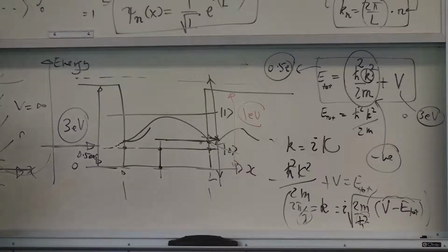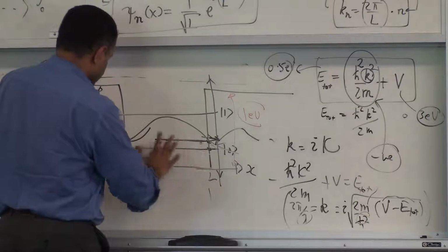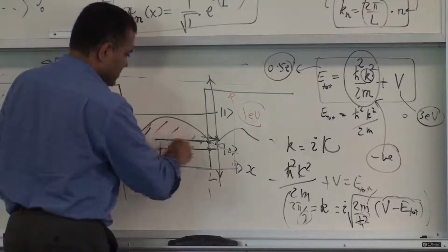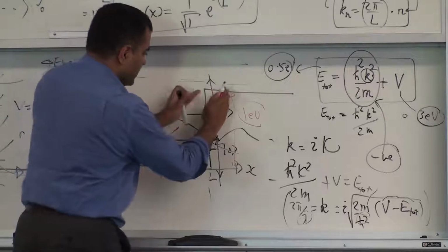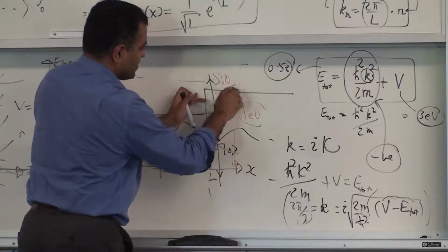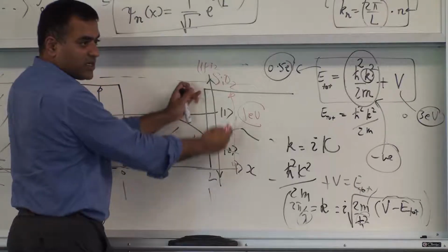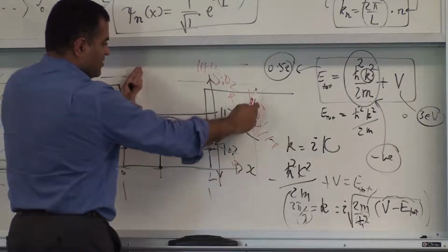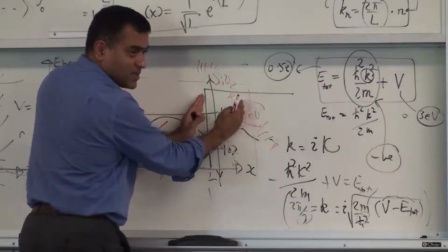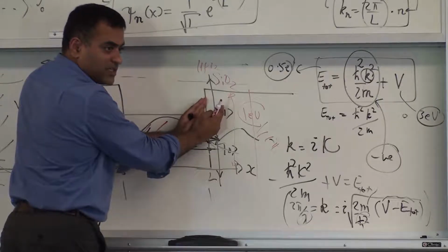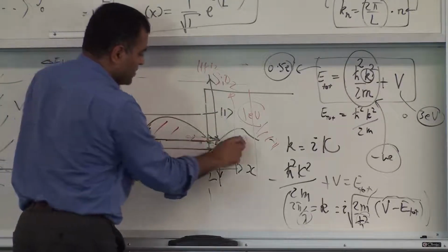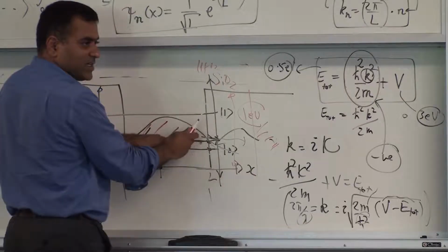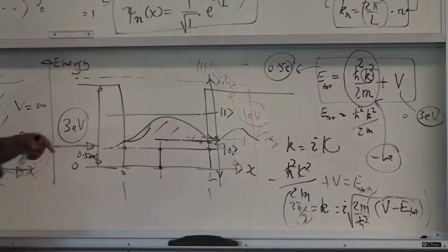And in semiconductor devices, this is actually very important now, because as you make a transistor small, in a silicon transistor, the electrons doing all the current flow are sitting in a quantum well like this. The barrier here is silicon dioxide or hafnium dioxide as a high-K dielectric, an insulator, and then there's a metal on this side. Because transistors have become very small, this thickness has shrunk to a couple of nanometers. Then you have a problem because the insulator is not going to be able to hold back the electrons. They will tunnel into the metal. That's called gate tunneling.